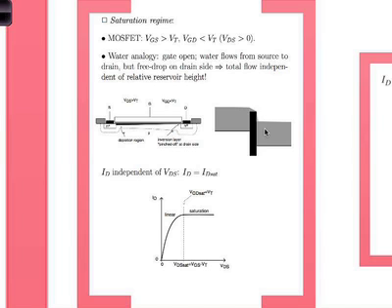But on the drain side, there is free drop. Essentially, the total flow is independent of the reservoir height. So this is always higher than that, which means that if the gate is open, this flow can happen irrespective of the drain to source voltage. In other words, the drain current becomes independent of the drain to source voltage, which is the same as what we've had before, the saturation. So I_D is independent of V_DS.